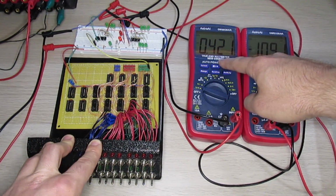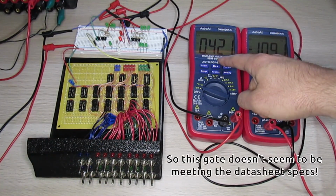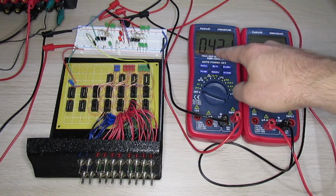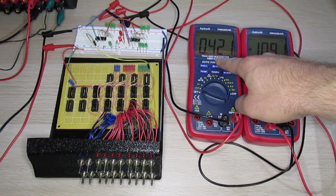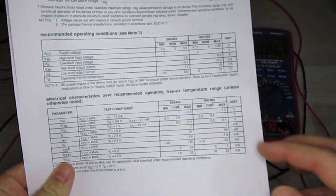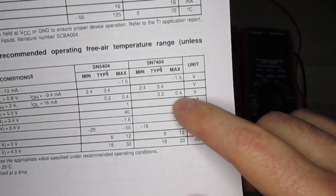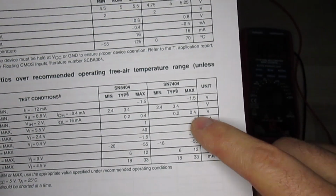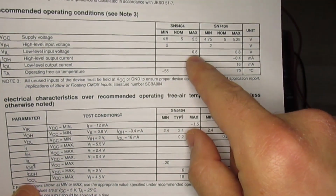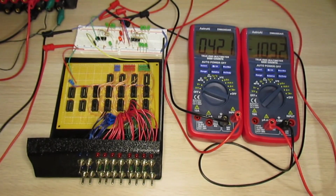You can see the output low voltage is 0.42 volts now, and the datasheet promises that it will never go above 0.4 volts. So this is actually a little bit outside the range that the datasheet promises. But even though it promises to never go above 0.4 volts, even if it does, it should still be okay because the inputs to the gates are willing to accept 0.8 volts. So everything still works fine.